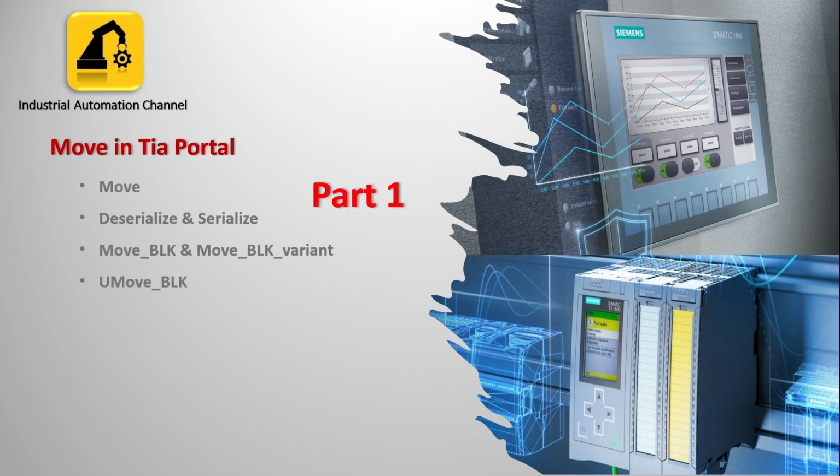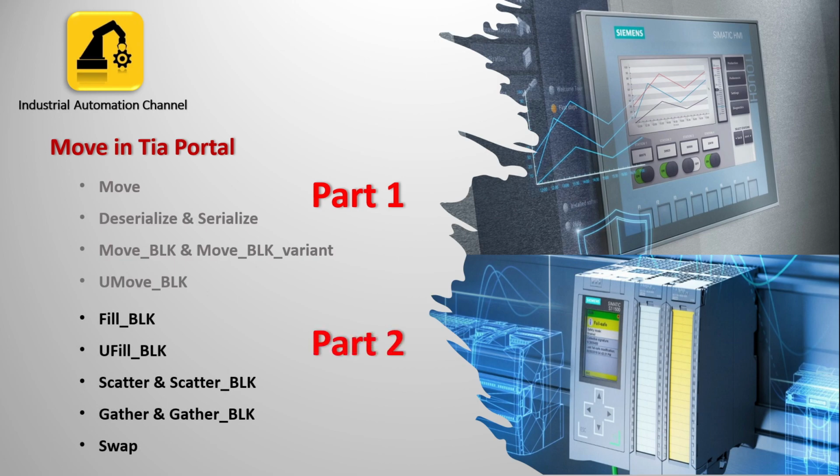In the previous video we learned some move operations in TIA Portal like simple move, serialize and deserialize. Today I'm going to talk about other operations including fill block, scatter, gather and swap.